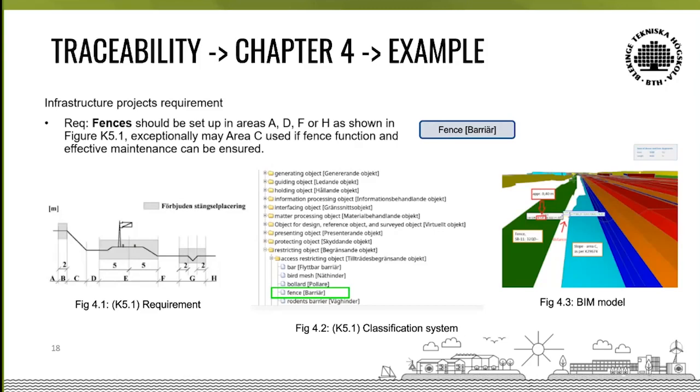The track should be somewhere there. This green color is the fence, actually, and this greenish area is the slope. And here is where the fence is situated. We measure the distance between the slope and the fence, and we found that this distance is less than 2 meters in this area.